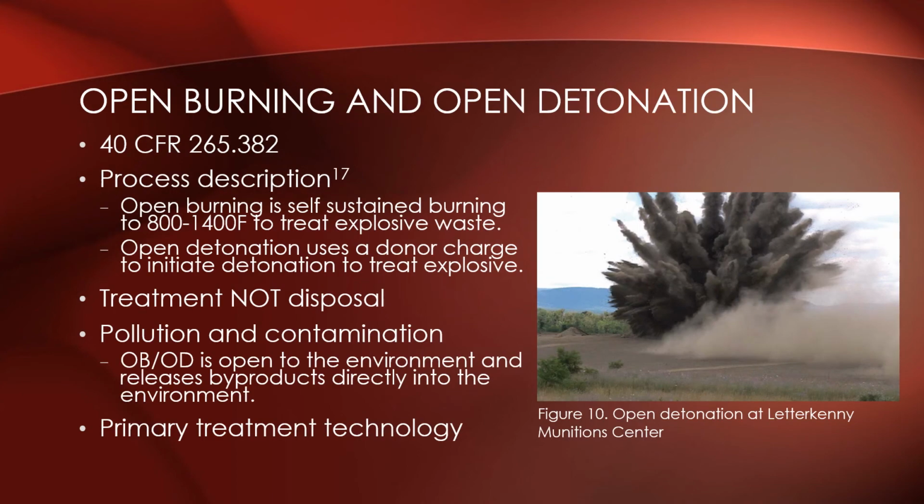Per 40 CFR 265.382, open burning or open detonation of any hazardous waste is illegal. However, there is an exception for open burning and detonation of explosive hazardous waste. Open burning and open detonation are uncontrolled treatment technologies. OB is a self-sustained combustion process and entails placing the explosive waste into a burn unit with dunnage if necessary, igniting the dunnage and fuel, and burning to a temperature of, on average, 800 to 1400 degrees Fahrenheit.